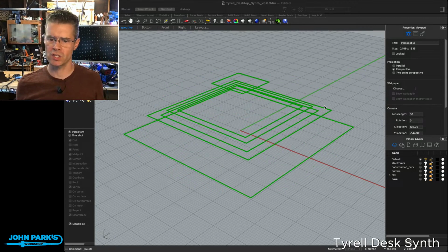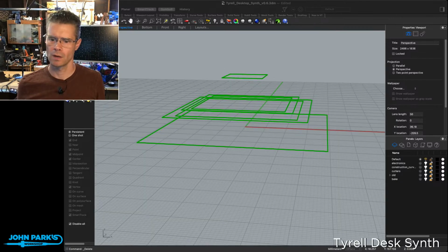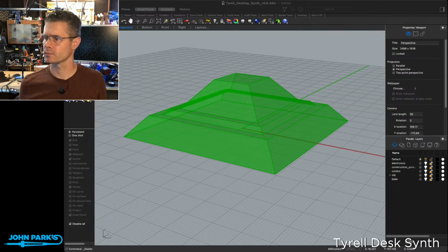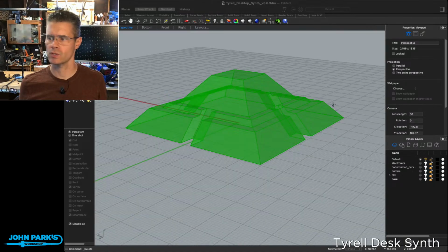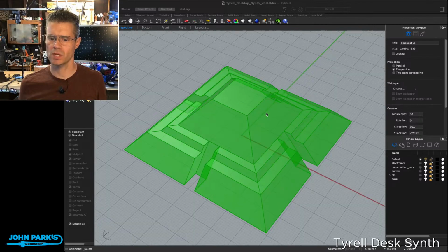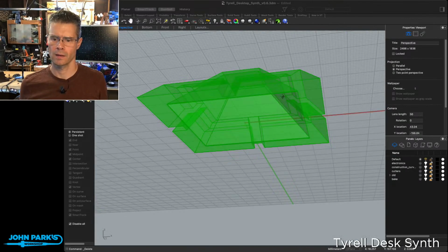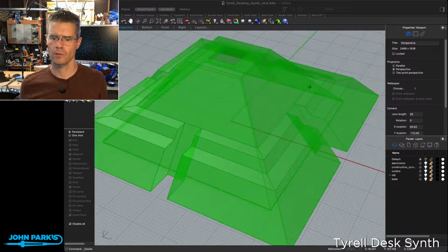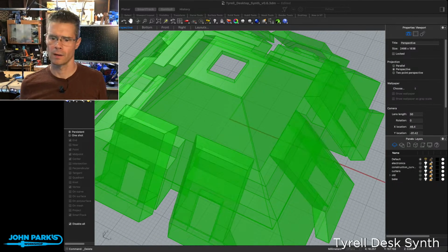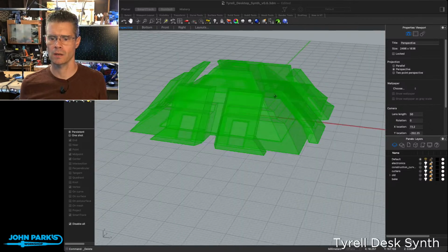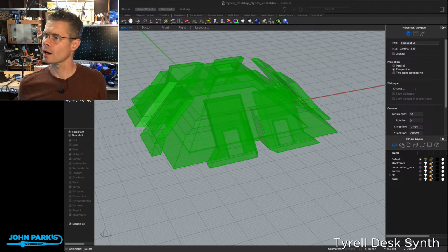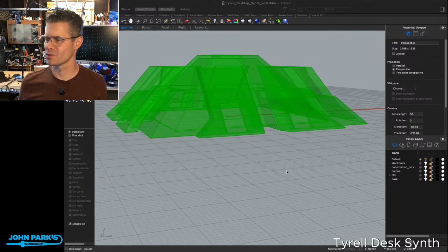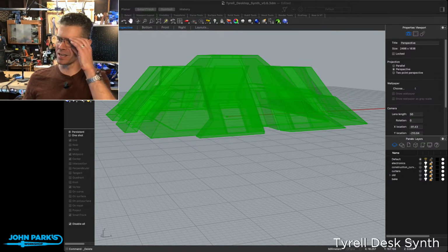Then for the pyramid itself, I actually lofted some curves into this shape, capped it, cut out some little columns out of there, carved the inside out, carved that chimney out of the top, combined these things, scaled it all up bigger, which was easier to do at that step rather than go and fix my curves, which probably I should have, but I was being lazy.